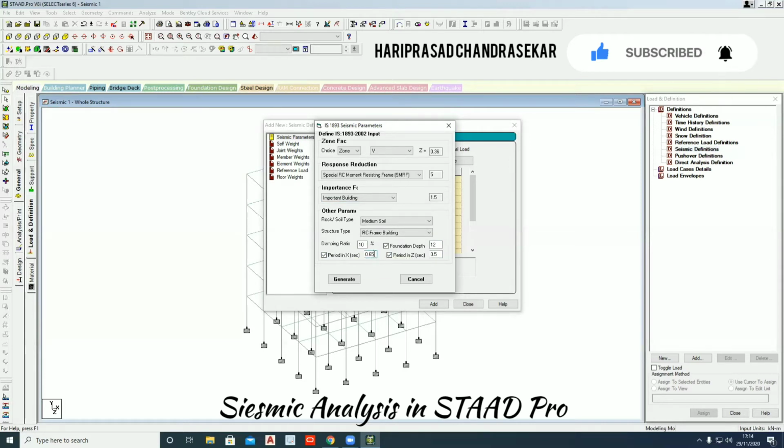These values, you need to study your code of practice and find the right formula and the right numbers. In every code of practice, that code book, you will have lots of formulas, and you need to input the values in those formulas and find the final numbers. These numbers I'm not putting just like that. They came from that kind of calculation. You need to calculate things like this damping ratio and everything. I'm just putting values like that here, but you need to calculate and input your own values.